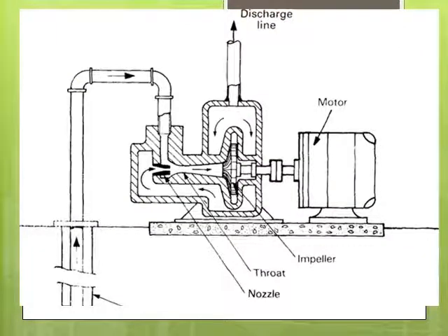This is a cross section of a jet pump. Kind of tricky to follow. The water comes in here from your well or pond and gets sent through the pump and then gets shot out the top to your irrigation stuff. What you'll notice is that some of the water can go around this casting and come out the bottom and actually recirculates through into this jet orifice and shoots around again, right? That some of the water exits and some recirculates.